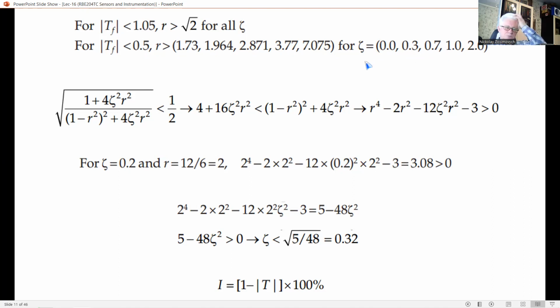And next, suppose that the device in our figure has an undamped natural frequency of 6 Hz and a damping ratio of only 20%, 0.2. Suppose for proper operation, it is required that the system achieves a force transmissibility magnitude of less than 0.5 for operating frequency values greater than 12 Hz.